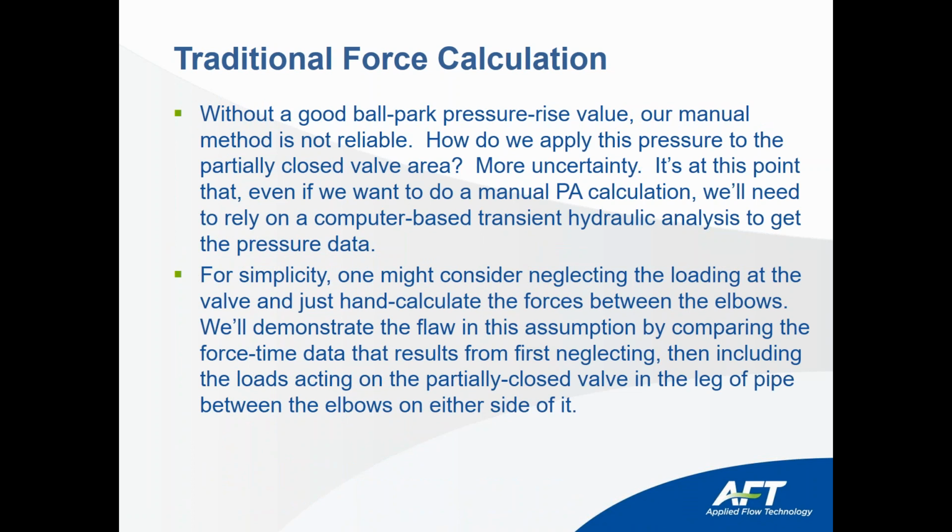So how can we apply this pressure if we have a partially closed valve area? At this point, we know we cannot do manual calculations, and we need a computer-based transient hydraulic analysis to get the pressure data and be able to estimate accurately the forces generated in the system.